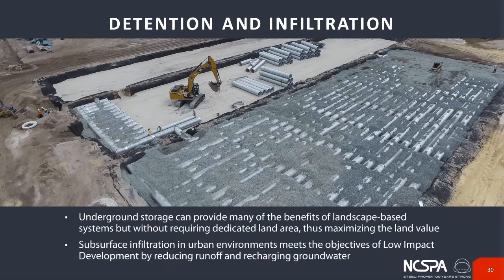So when you go in and you build buildings and you build parking lots and create a lot of impermeable area within a site, typically that would create more runoff that would go into the local streams and storm sewer systems, and could tax those systems and render them to be insufficient. So, in order to overcome that, most agencies will say that you have to design your development such that the runoff after the development is completed does not exceed the maximum runoff that was there pre the development.